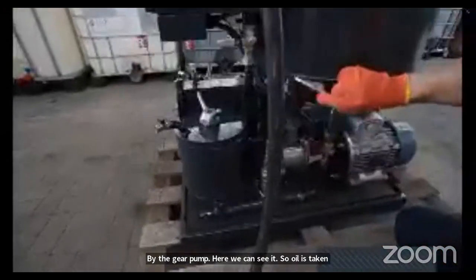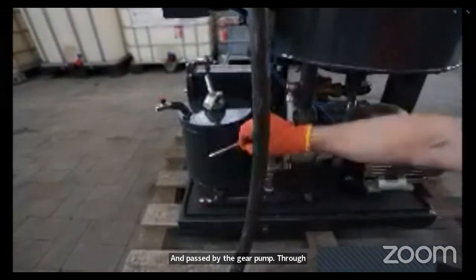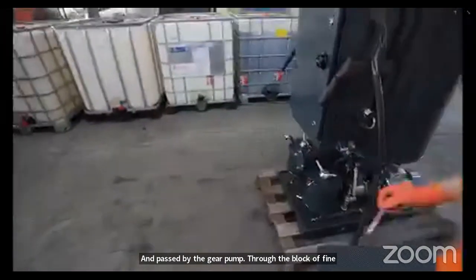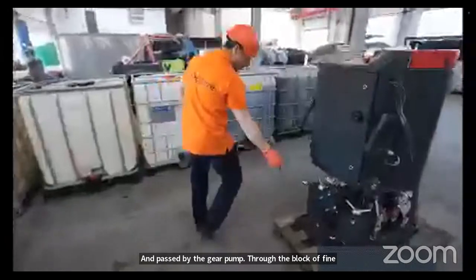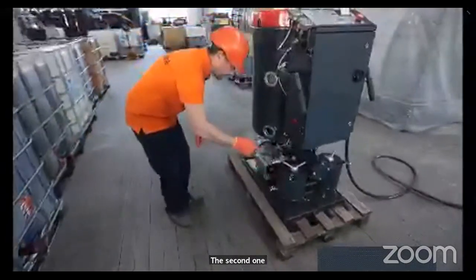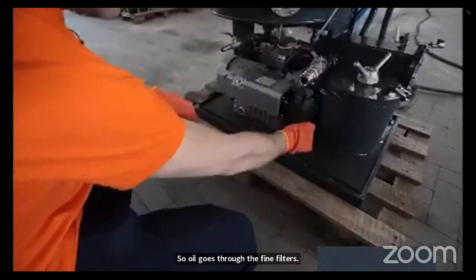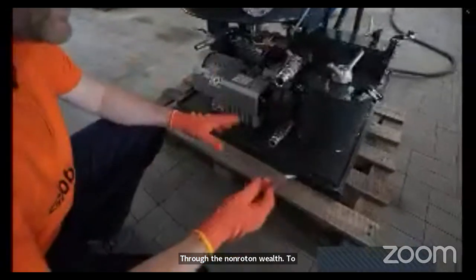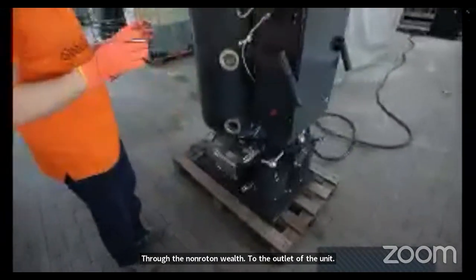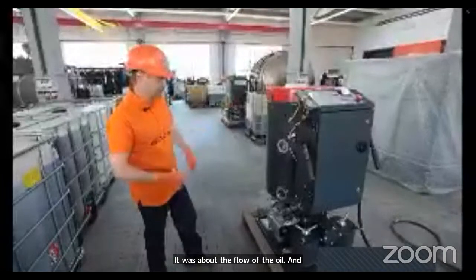So oil is taken from the vacuum chamber and passed by the gear pump through the block of fine filters. This is the first one. The second one. So oil goes through the fine filters, through the non-return valve, to the outlet of the unit. It was about the flow of the oil and the material exhausted.